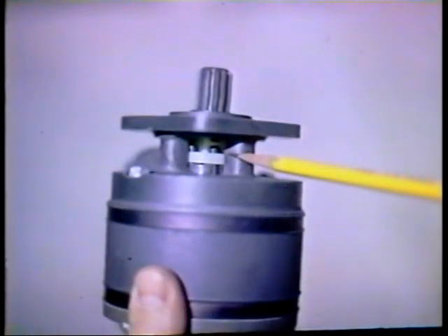When washing an aircraft engine down with degreasing solvent, gunk, or water, it is advisable to place a shop cleaning rag over the mounting flange area of the pump, that is, the area where the coupling is visible. This will prevent accidental forcing of the cleaning solvents or gunk into the working parts of the pump, which would cause serious damage to the carbon moving parts.